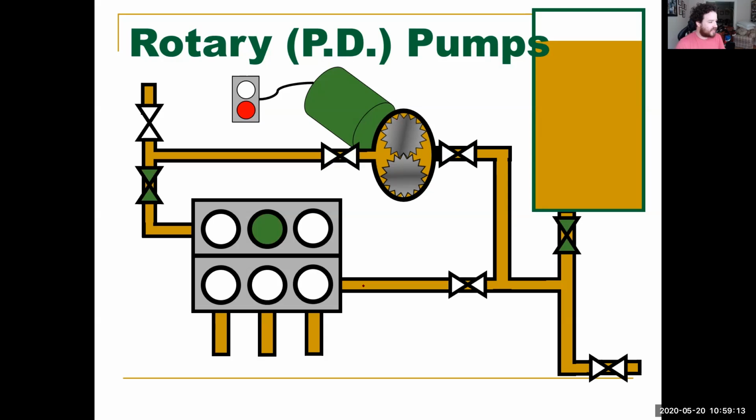So the biggest thing is to choose a valve on these systems. Usually just do your discharge. Not the worst spot in the world to choose because you're going to be operating next to the pump anyway. But close a valve. The biggest reason for that is that you don't want any backflow. You want to kind of split the system in half.